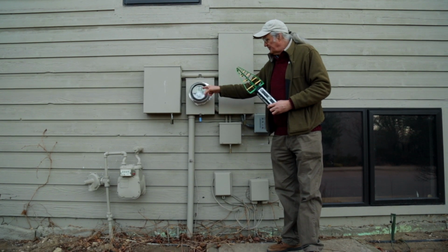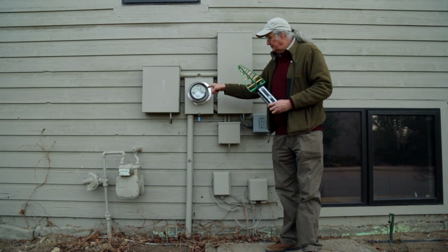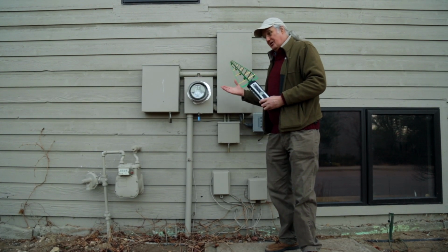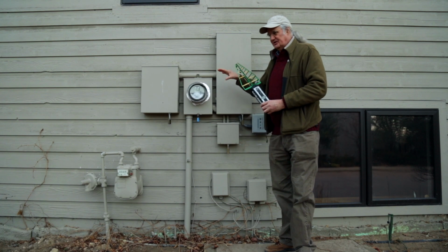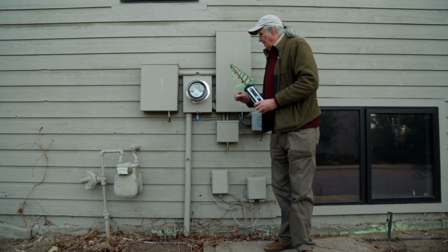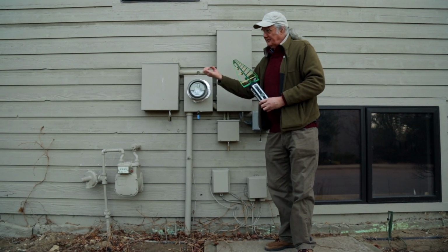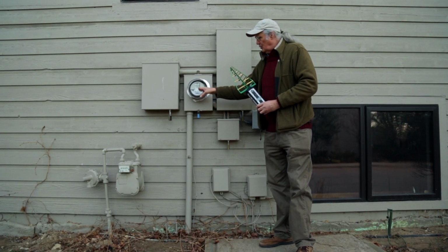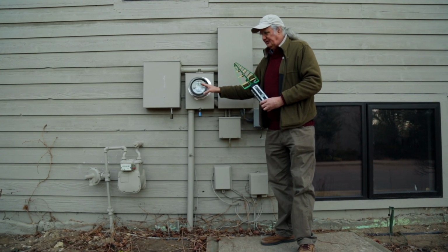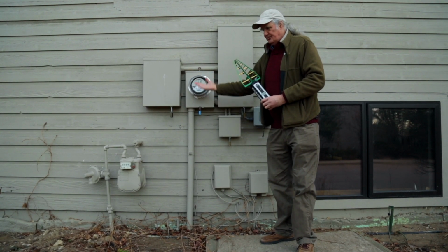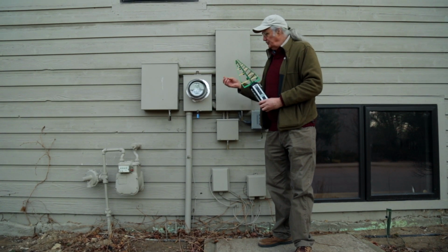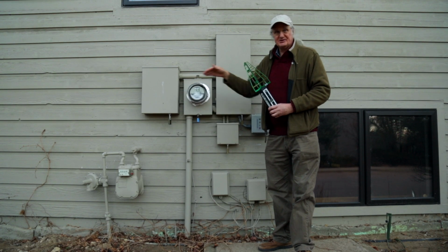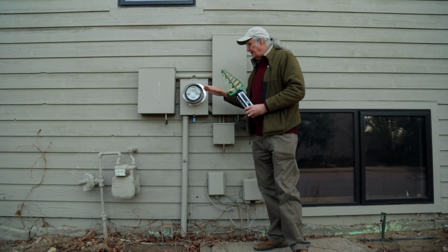And the difference between a smart meter and the old analog meters is, number one, it's digital. The smart meter is digital. The analog meters are analog. They're mechanical. There generally are no electronic parts in them. Although I have seen an analog meter with a radio transmitter in it, but generally that's not the case. And not all digital meters are smart, in the sense that not all of them transmit beacon signals throughout the day to connect to each other through what's called the neighborhood area network, the mesh network. But in this case, that is what happens here.